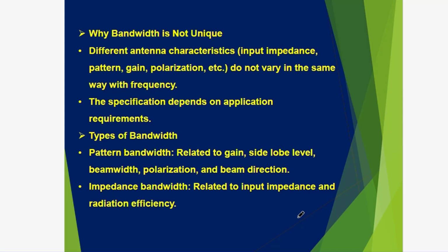Coming to the impedance bandwidth, it is related to input impedance and radiation efficiency. Same way as pattern bandwidth, you can define impedance bandwidth as the range of frequencies within which the input impedance and radiation efficiency are at acceptable values compared to the center frequency.